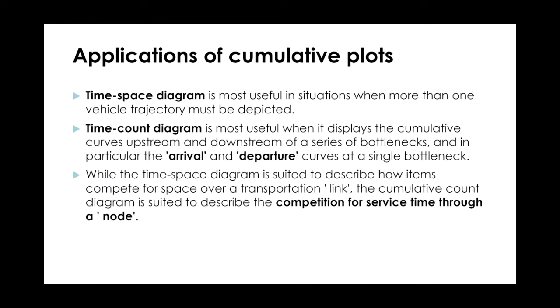Going back to the time and space diagram, if you remember, it is one of the most useful tools in traffic analysis. When we have each trajectory, we can follow every trajectory in a time and space diagram and calculate so many things about traffic, like do the shockwave analysis, calculate flow, speed, density, etc.